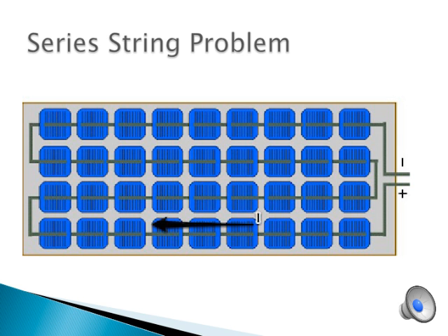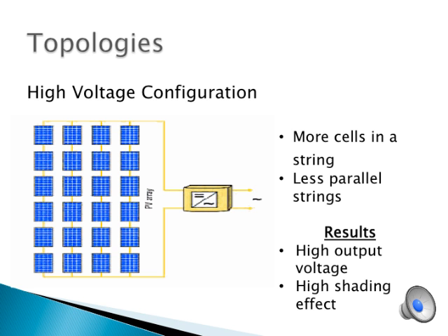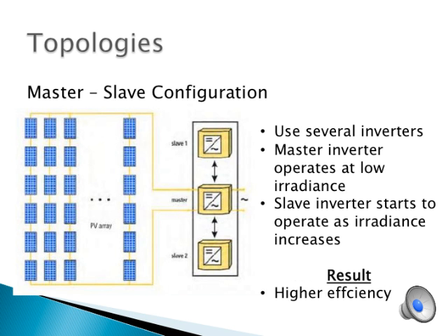While the production of CIGS costs less compared to silicon-based solar cells, the typical conversion efficiency of CIGS solar cells is lower than that of silicon-based solar cells. Traditionally, CIGS cells are fabricated using vacuum processes, including co-evaporation and sputtering. Recently, some non-vacuum processes were developed, which may result in lower production costs in the near future after commercialization of such technology. Now, Tony will be talking about several types of inverters used in solar power generation systems.